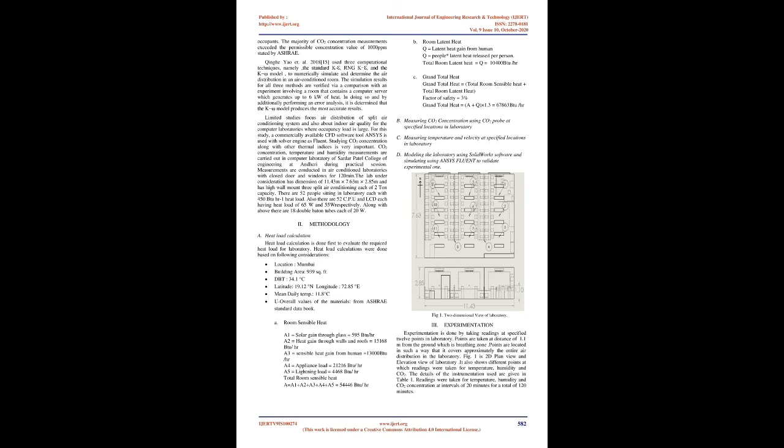M. Rahman, 2016, simulated a school auditorium using the computational fluid dynamics technique to evaluate airflow velocity, pressure, and temperature. Two modeling scenarios were investigated, one being the existing system and other being the system designed using displacement ventilation. CFD simulation for both the existing and proposed systems demonstrates stagnation of air and higher temperatures in the back stalls and circle area.